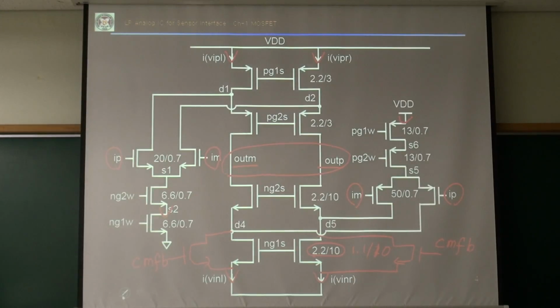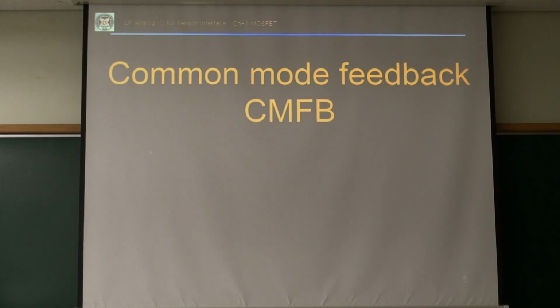Ideally, this CMFB voltage is the common mode output voltage minus the reference voltage plus some desired voltage.